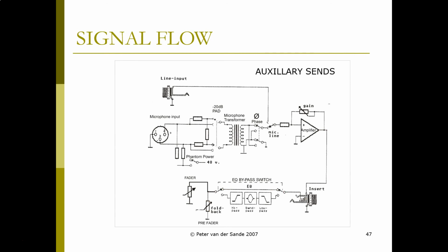Over on the right-hand side, we're looking at our foldback, which is going to be pre-fader. And if you remember, foldback is the monitor send for the musicians. So the foldback output is now our orange connection, or orangish red, and that again gets sent to the performers, and it's pre-fader. So what we do with the fader doesn't affect what they hear in their headphones, in-ear monitors, or on-stage speakers, because it's really obnoxious if our level changes affect what they hear. The more we turn it down, the more they play louder, for example.